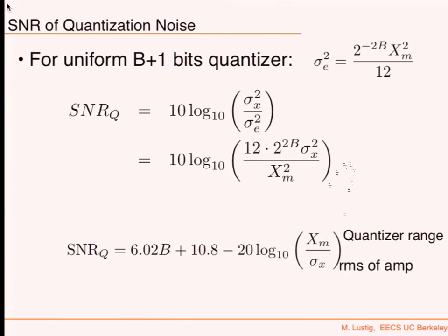So what does this mean, actually, if you think about this? This is loss of SNR, right? Kind of makes sense. If my signal only varies, like this is my dynamic range that I'm going to be digitizing, and my signal only occupies a small part of that dynamic range, then I get a hit because I get more quantization.